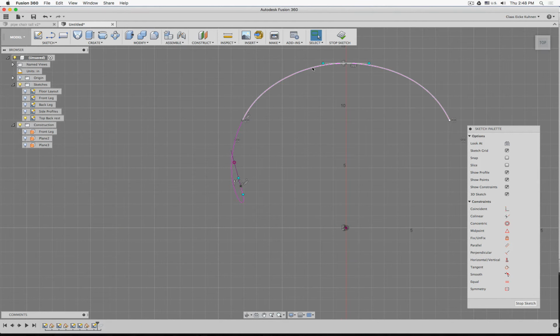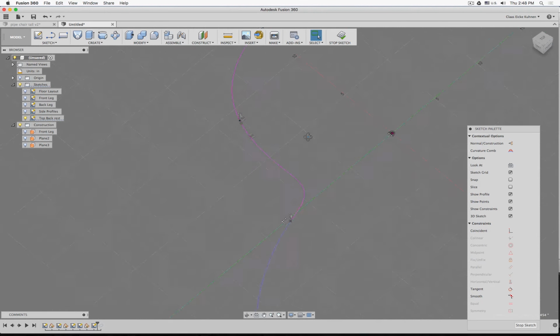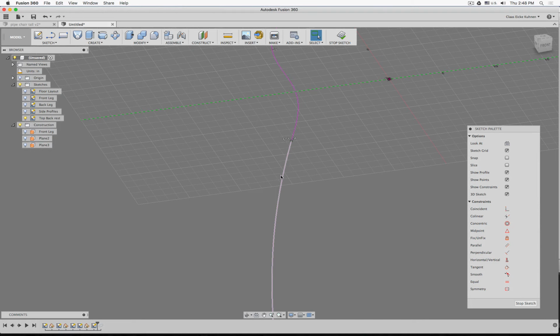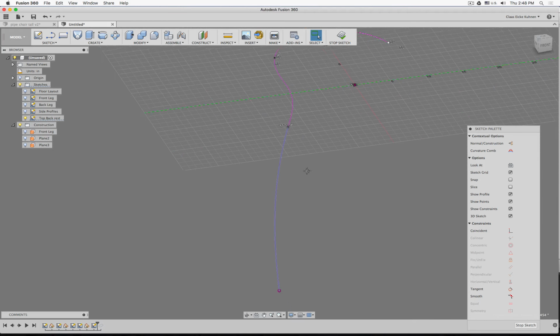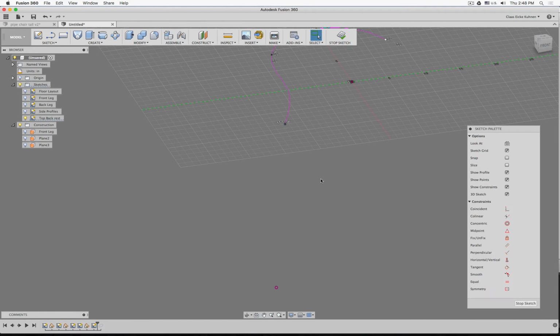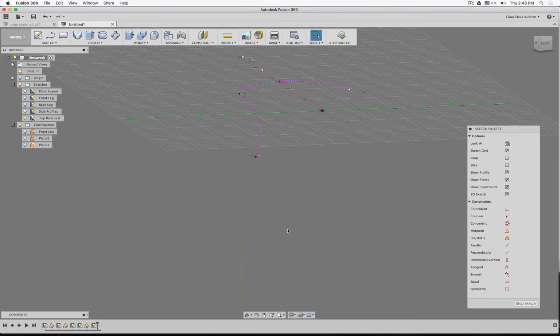And that's pretty fantastic. You see this curvature or the shape we can really see at the beginning here before it blends into this line. This is actually a 3D line, a projected 3D included sketch. When we press F, we can actually hide it, so I don't have to deal with it all the time. And to show it later, you just go over it and press F again, and there it is. Could also make this a construction line. Okay.